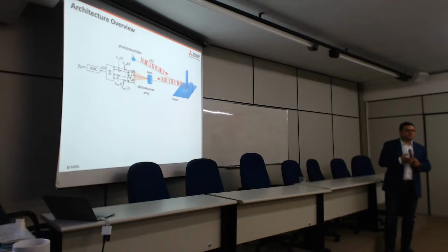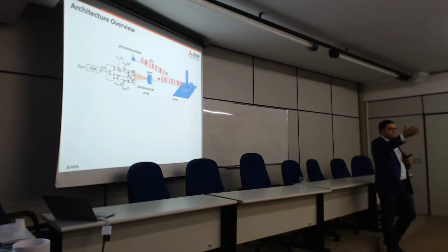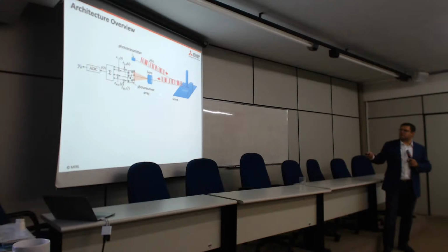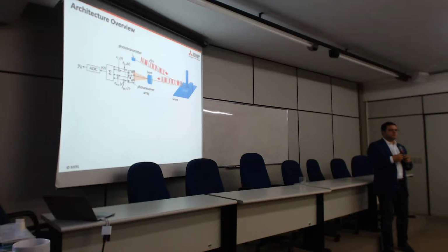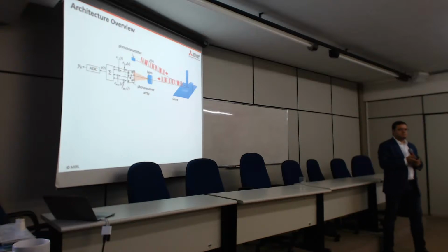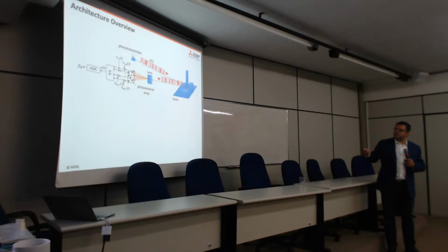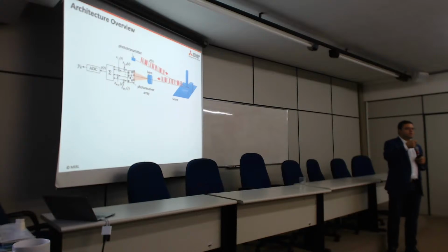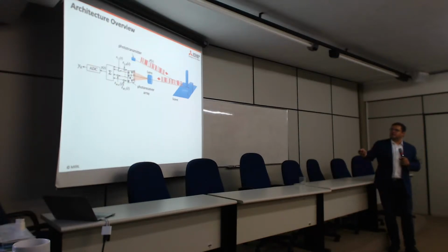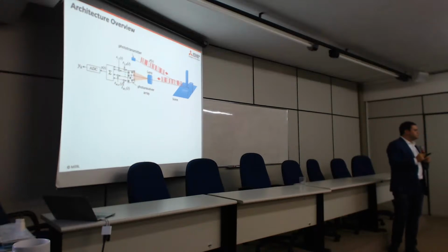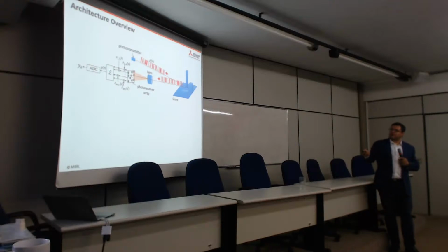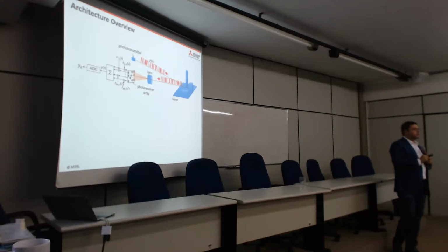We're going to transmit a pulse. Now that we know light coding is cheap, we'll send a pulse that is coded, and that's important. This will go through a lens. It will go to our array, which is now a dense array, which can be as cheap as your CCD or your CMOS detector. And then each of those sensors will get multiplied very quickly with a binary pulse. We will code it. It's something that people doing communications find very easy, and you can code it at a very high rate. So every pixel has been multiplied with its own code. Okay? And then we add everything together,